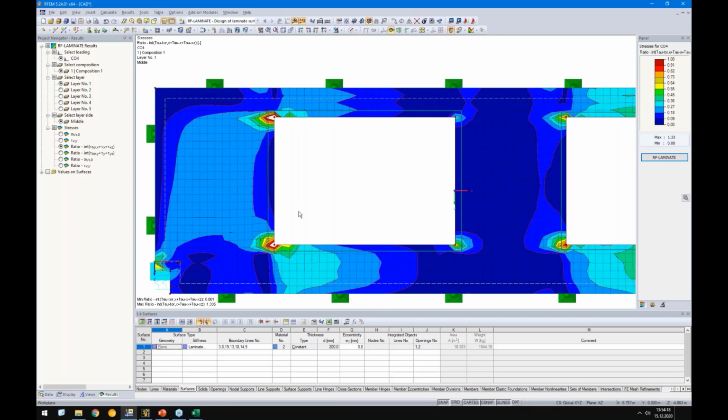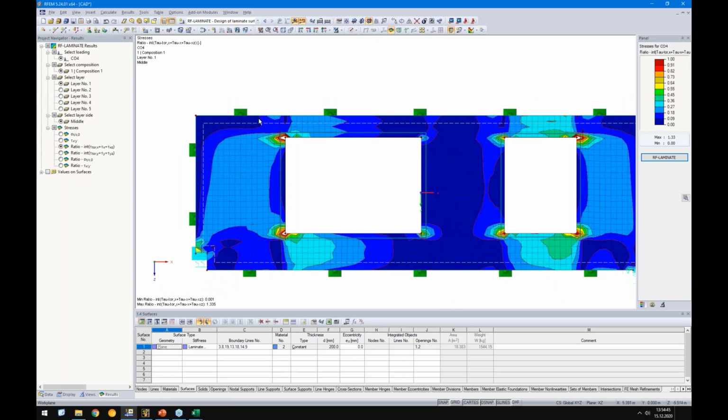Unfortunately, we have no possibility in timber to distribute any stresses to fix the singularities, or to distribute the stresses with a plastic analysis, so a nonlinear plastic analysis, since we use only a linear elastic material behavior in timber, which is actually common. So there is no real way to check it also for timber.